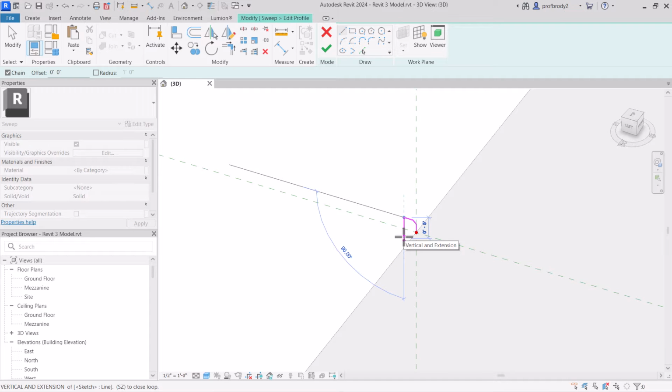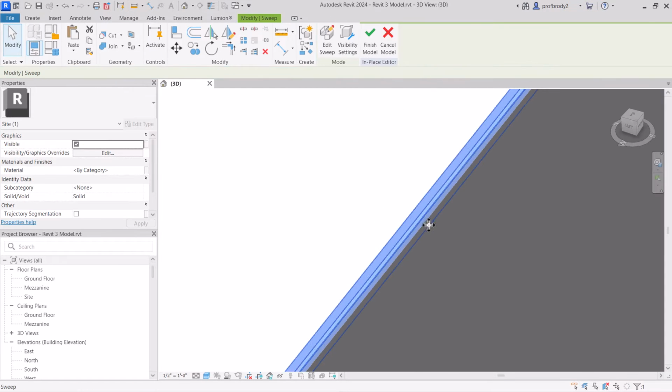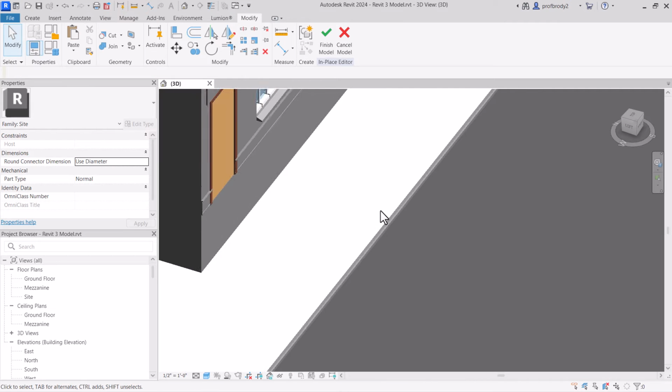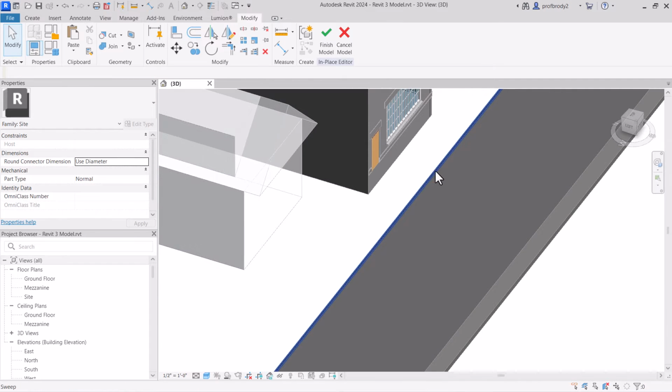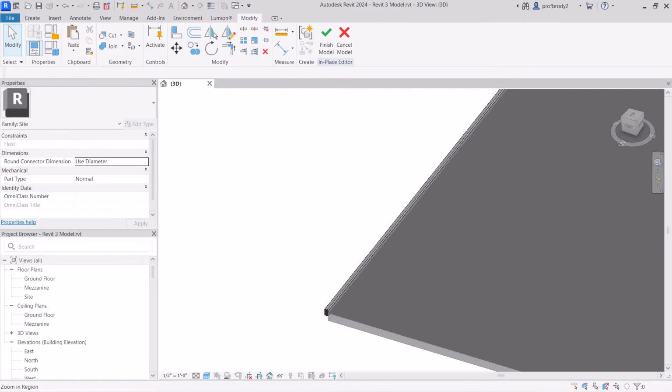You can also make it go down below the surface, which again is kind of handy because sooner or later you're going to end up doing a site section. These will show up very nicely in site section. So click the checkbox and the checkbox, and like magic, you have yourself a component, a model in place component that you can use in any situation, which is super handy.